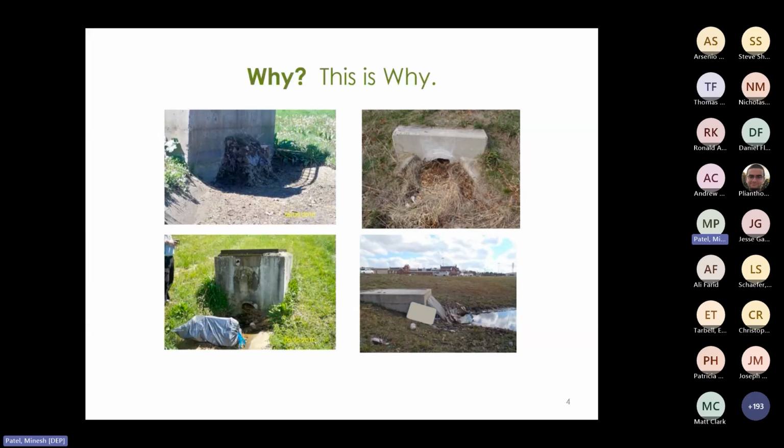That means the drain time of a parking lot, for example, or whatever else is upstream may even be longer, which can cause flooding. It can also mean a basin takes longer to drain, which can lead to a possible creation of a mosquito breeding ground. Plus, they can attract unwanted wildlife or can even lead to complaints from the public. All of this is stuff we really want to try and avoid.